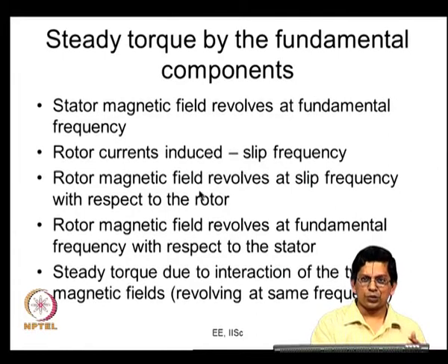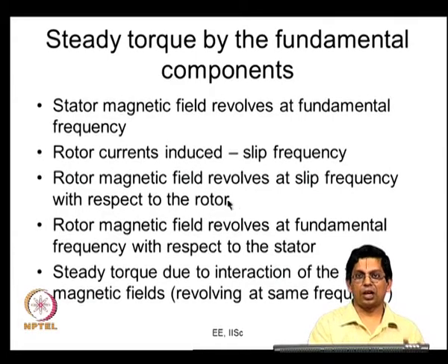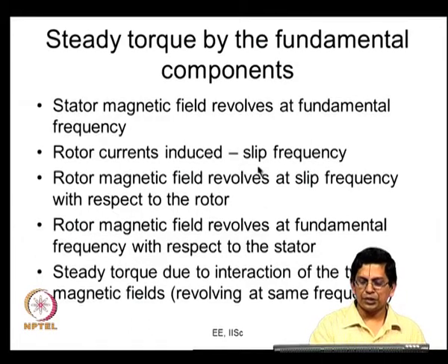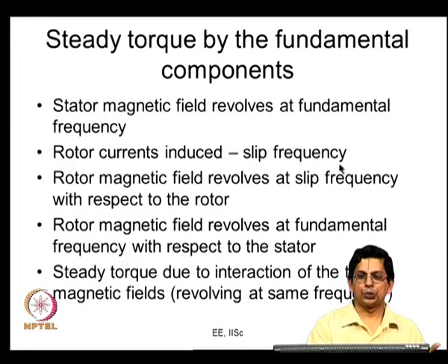So, it goes to something close to 50 hertz, maybe 49.8, 49.5, that depends on the load torque. So, it goes to some frequency which is close to 50 hertz like 49 or 49.5. So, the slip frequency is 0.5 or so. The slip frequency at which it settles down is dependent on the load, or it is a measure of really the load torque. So, this is how you can explain why an induction motor is self starting.